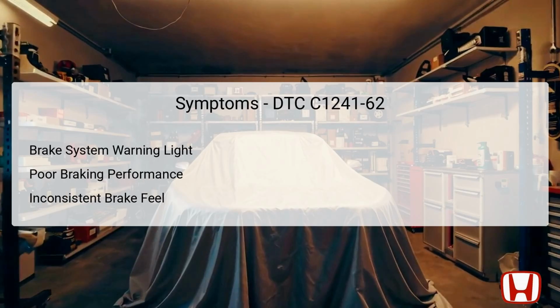Drivers may observe several symptoms associated with DTC C1241-62. Most notably, the brake system warning light may illuminate on the dashboard, signaling a need for immediate attention. In addition to the warning light, the vehicle may exhibit poor braking performance, characterized by reduced stopping power or extended braking distances.